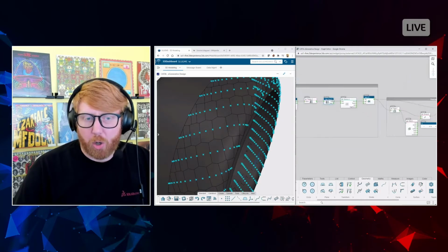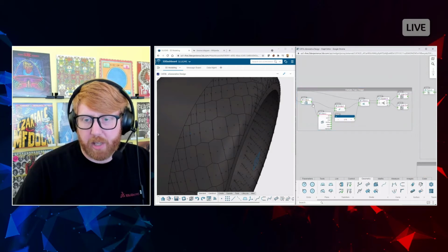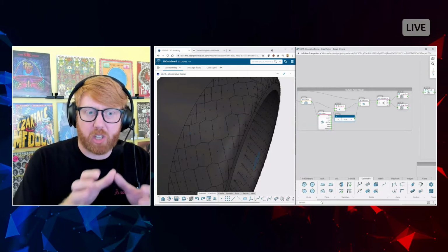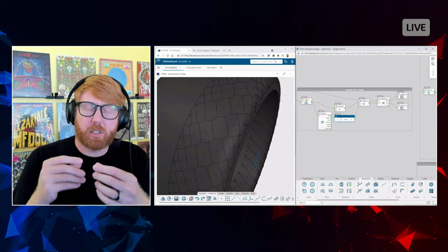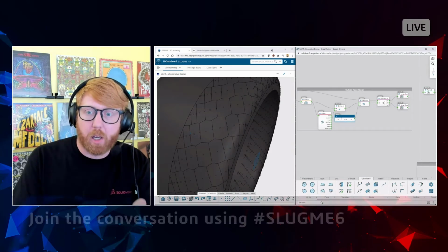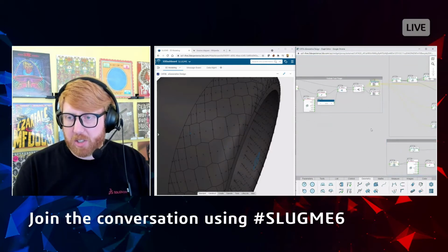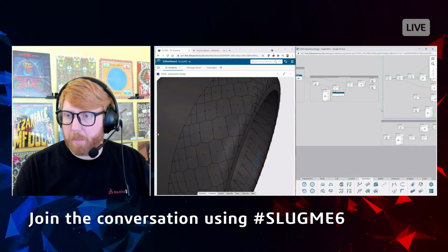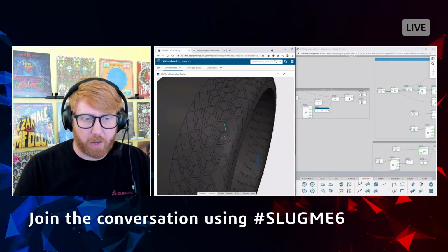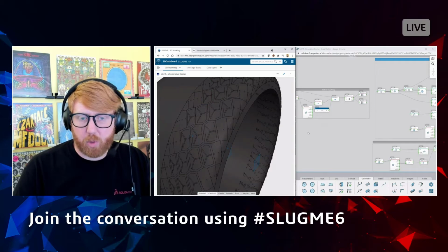Okay. So now I have that split face, and then I do some of the same exact stuff here where I'm doing the area, and then some function of the area. I'm basically saying everything that's at least 75% of the surface area of the largest one will be grouped into these larger portions, and then the other ones will be grouped into these smaller portions. And so I split them out, and I create a bunch of lines, so that we have all these ones going in the same direction here.